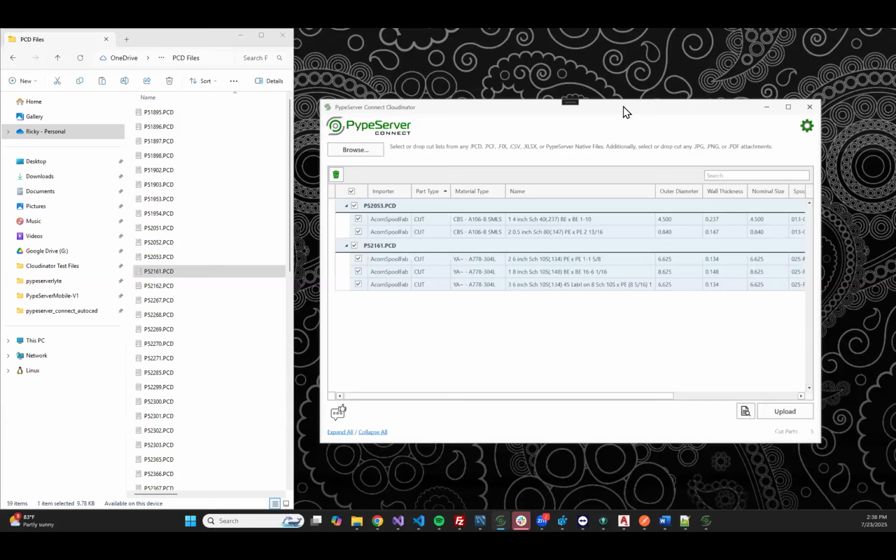So if it is an I-beam or a different shape, angle iron, something like that, we can parse through the ends of them, but we're not going to be able to automatically set up how to cut those ends. There's a lot that goes into structural, but we can get you the lengths at least, so you'll be able to get your structural components out of advanced steel and into a cut list easily and up through MSUITE.